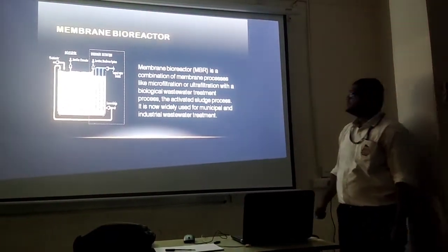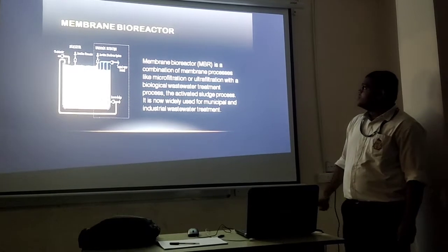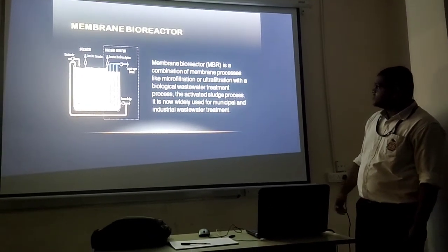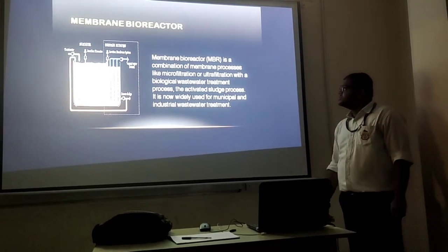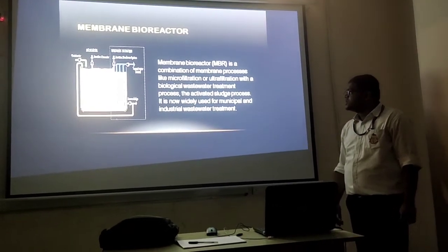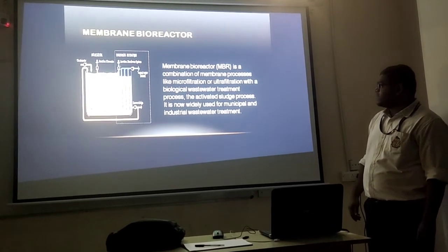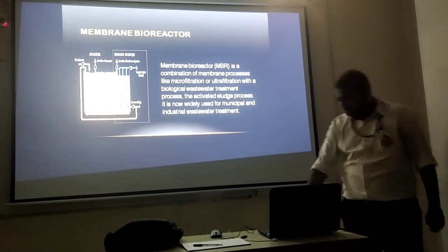Coming to the next one, the membrane bioreactor. A membrane bioreactor is a combination of a membrane process like microfiltration or ultrafiltration with a biological wastewater treatment process, the activated sludge process. It is now widely used for municipal and industrial waste treatment.